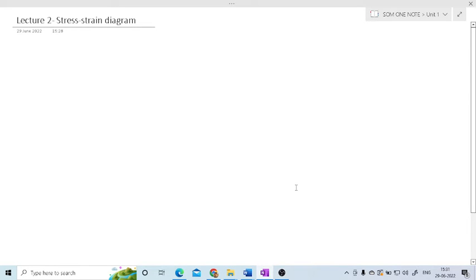Hi friends, so we are going to see lecture number 2 on strength of materials, the stress strain diagram. In the last lecture we learned what is meant by stress, what is meant by strain, and the relation between stress and strain, which is that stress is proportional to strain. If you remove this proportionality, then it becomes stress is equal to modulus of elasticity into strain. We know that stress and strain are proportional to each other.